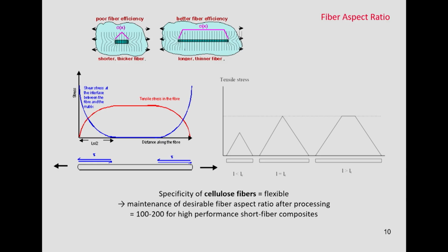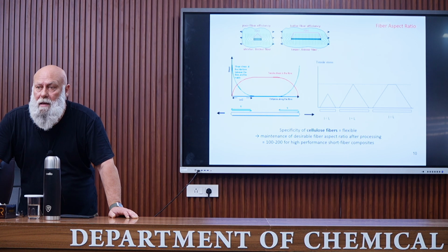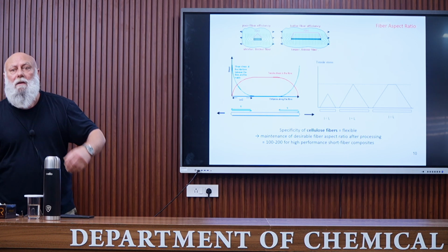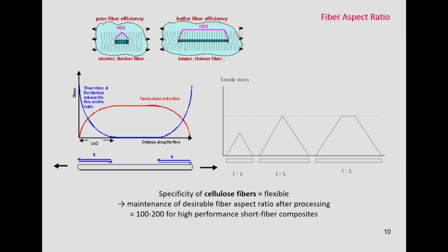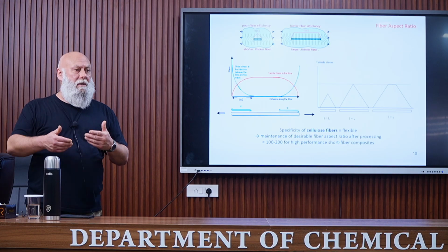One important thing is that to process composites, we have seen that there are different techniques. For thermoplastics, what is mainly used is melt blending, which can also be extrusion or injection molding, and in this process, high shear rates are applied. When considering glass fibers, usually the length of the fibers decreases during melt processing.